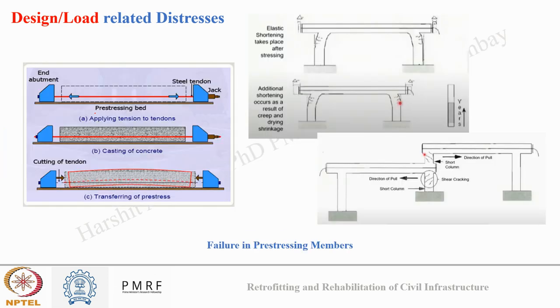Additionally, sometimes we also have pre-stressed members. So, what are these members? In these members, to enhance the performance of reinforcement, steel rebars are pre-stressed prior to casting, and then concrete is cast. So, here you can see a steel rebar that is provided tension by abutments, and after pre-stressing them, the concrete was cast over it.